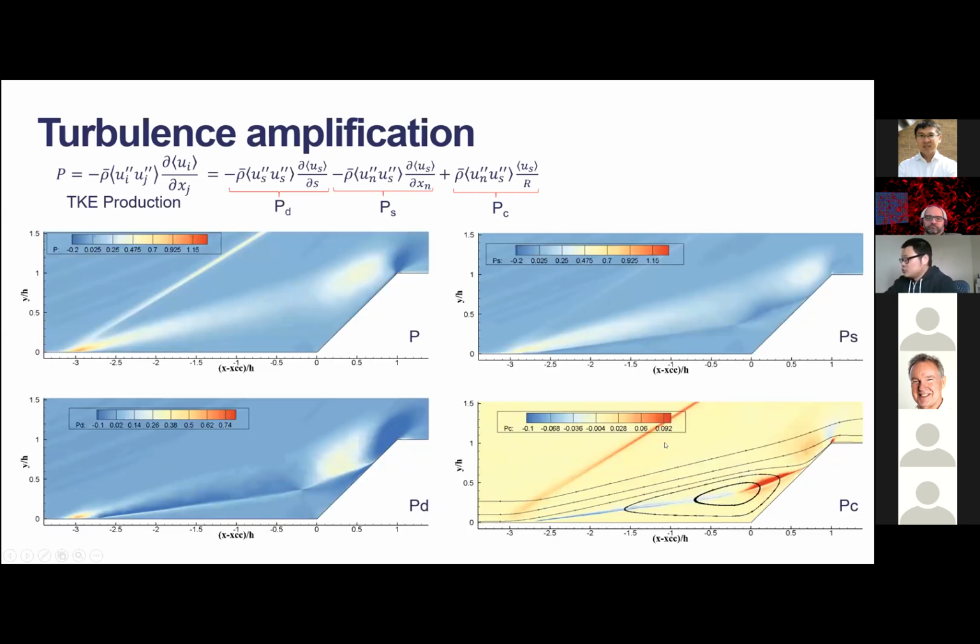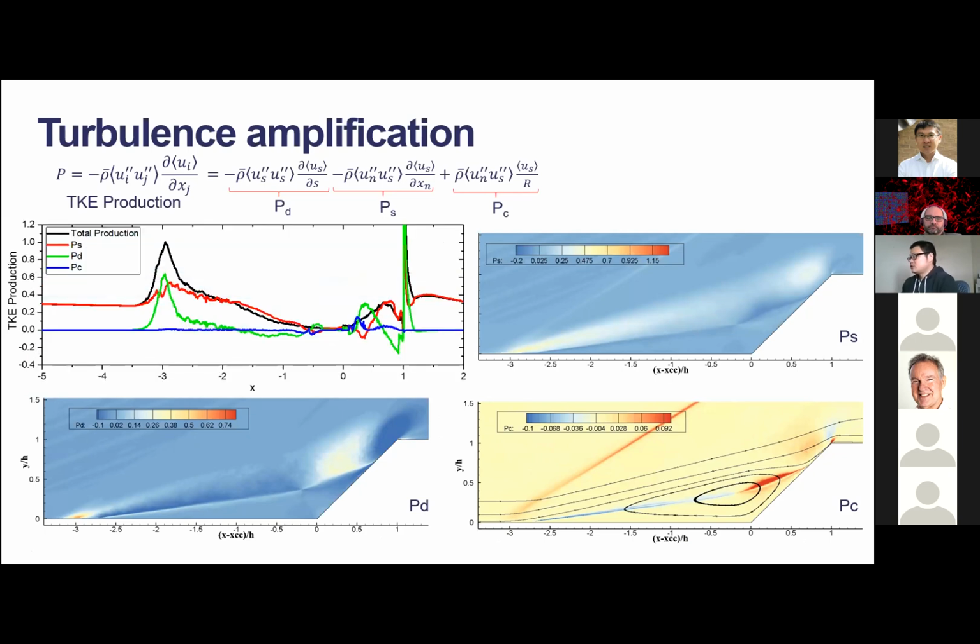Then we keep going on to the 45 degrees. In this case, the flow has a greater curvature effect. So then we try to study the different terms. For this case, the deceleration terms are much larger than the other terms, and things become very interesting near the expansion corner. We see that the deceleration terms switch quickly from positive to negative, like here.